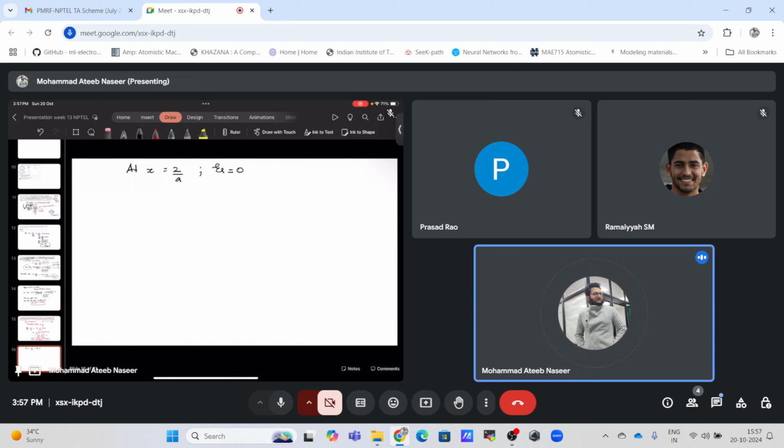Okay, so say that this depletion region ends at 2 by a, there will be zero electric field beyond it because there is no depletion region after 2 by a. At 2 by a, the electric field must go to zero because there is no charge inside the bulk where we have to terminate this electric field. Since we now have no electric field after the depletion region, neglecting the Debye length.